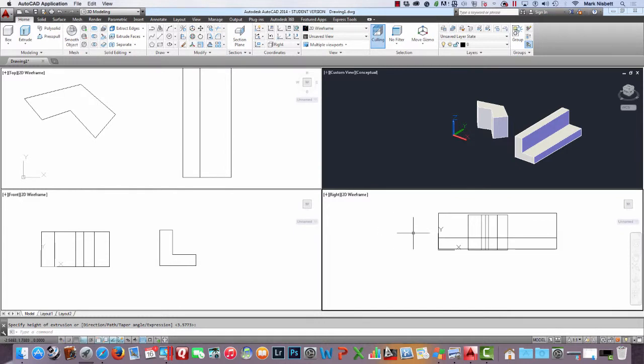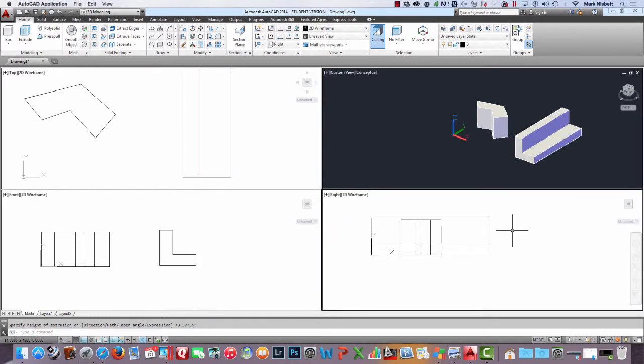And then in our right viewport, again, if I wanted to draw another letter, say maybe an M or something, we'll just turn off ortho for a second. We'll sketch this up kind of like this, put in an M, come down using our temporary tracking points.